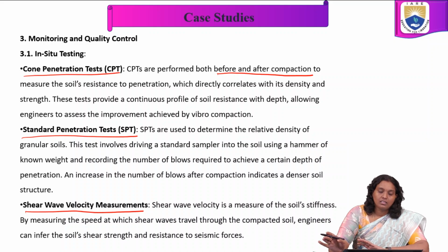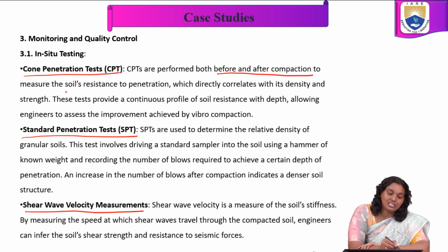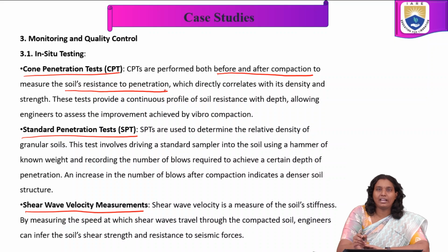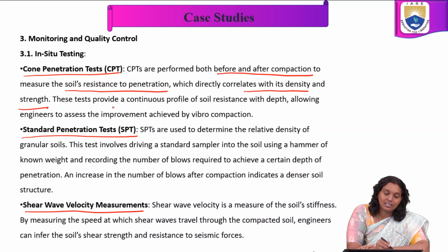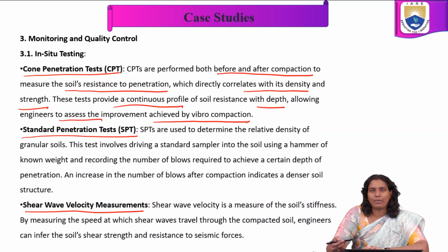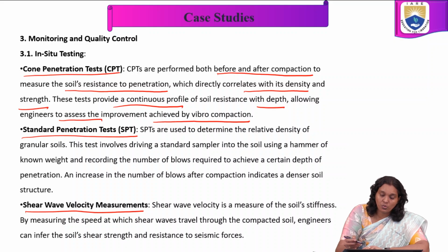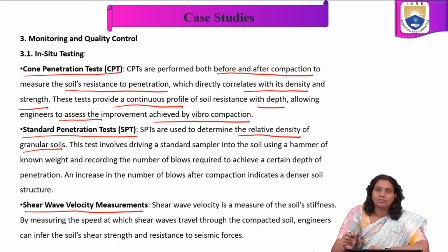Here the CPTs are performed before and after compaction to measure the soil resistance to penetration, which directly correlates with its density and strength. These tests provide a continuous profile of soil resistance with depth, allowing engineers to assess the improvement achieved by the vibro compaction.